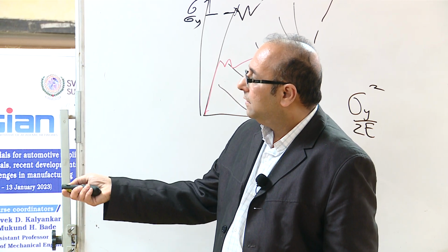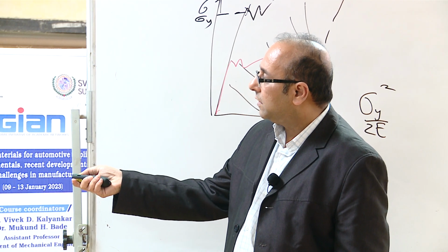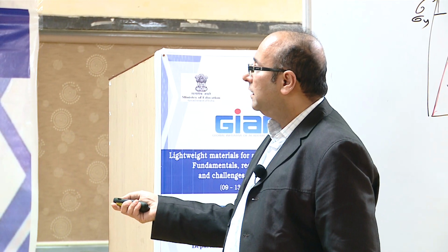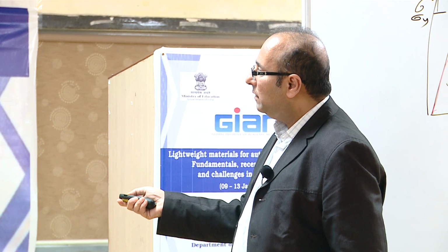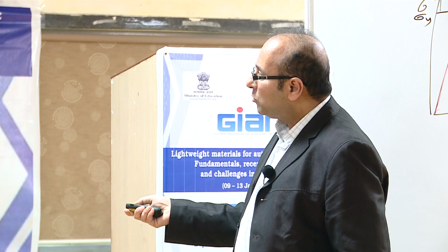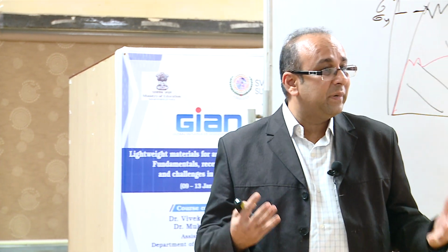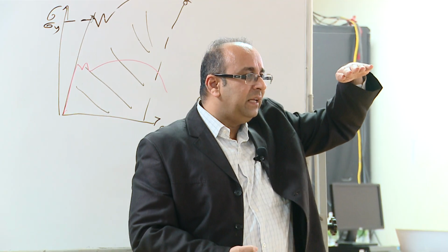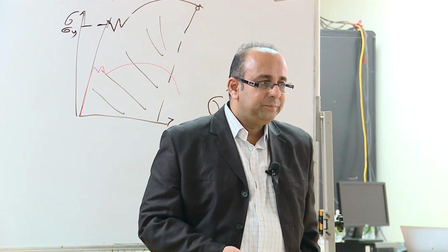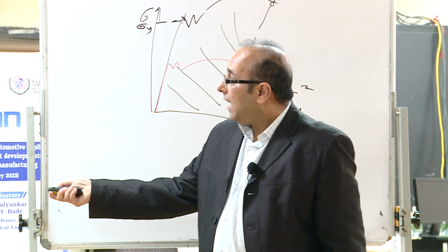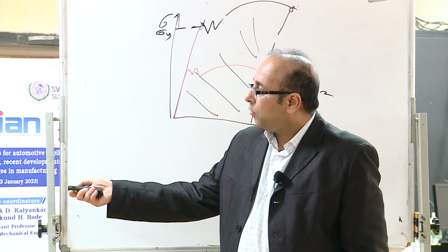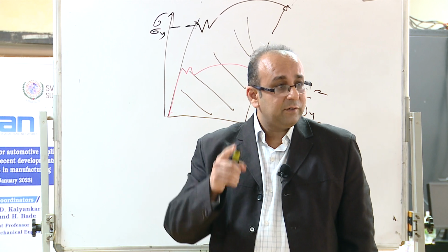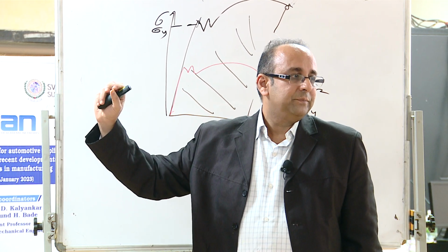Again on this part, which we know is our typical conventional part with so many different toolings. Some part is warm forming, majority of the part conventional forming, because this complex part is so difficult to produce at room temperature, impossible practically. The deep drawing of more than 150 millimeter is very difficult to produce this part. But I could do this part completely as a warm forming in some of the design, and then this part has a better crash worthiness than these 5 parts together.